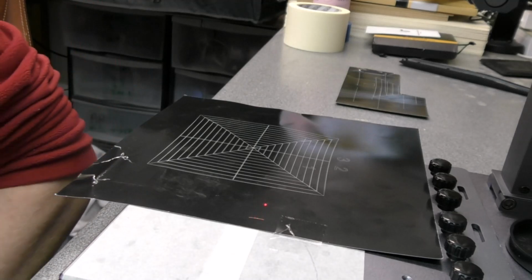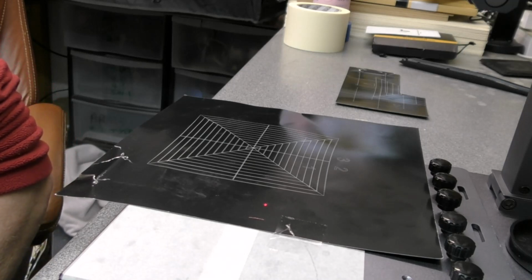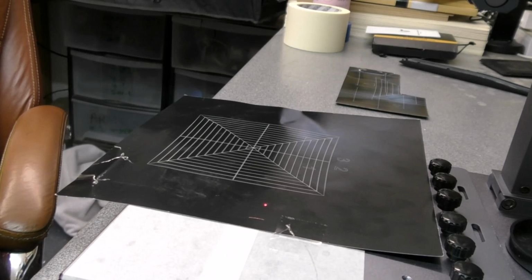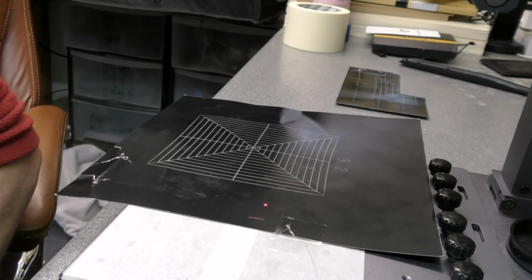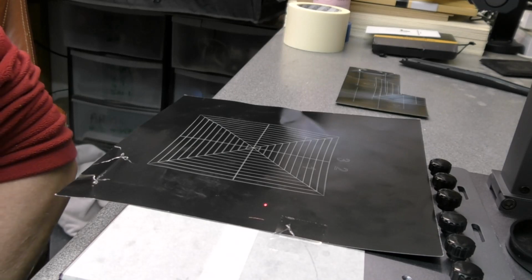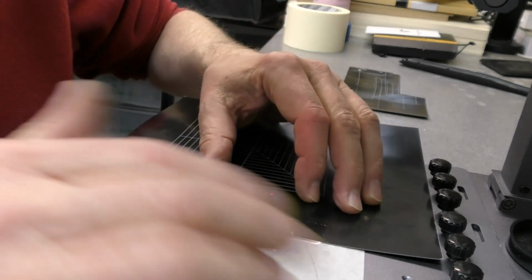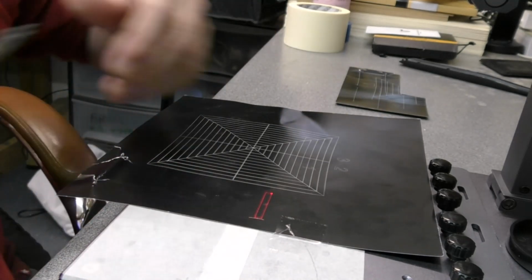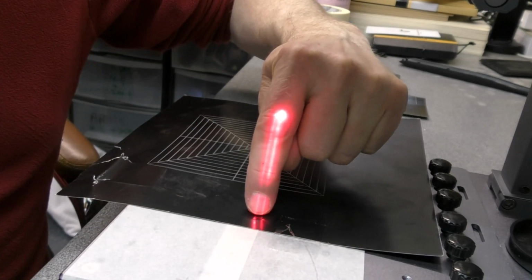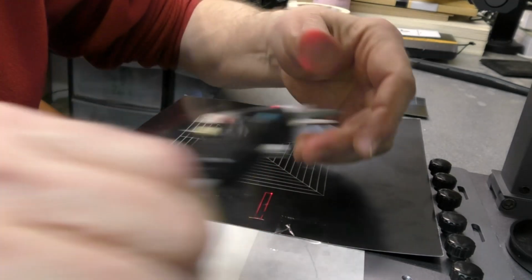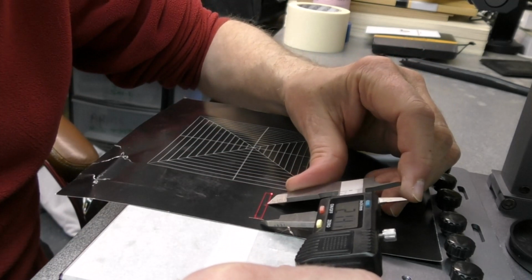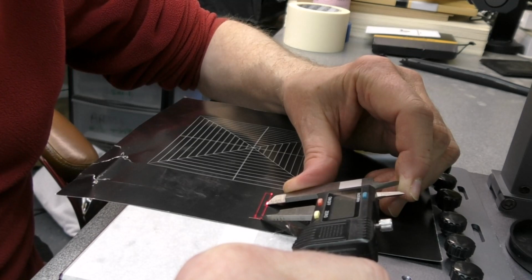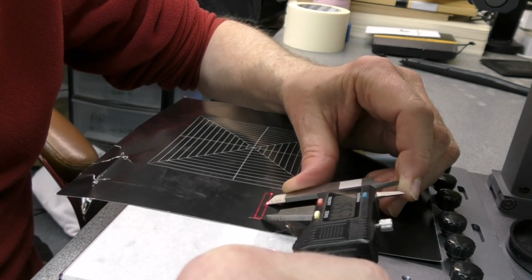So I'm going to go F3, red. We're going to change the offset back to 0.0700 and hit OK. Now we're going to do the red F1 again. Now this time, I really hope you can see this on the camera. This time the end of the box has been moved substantially back to where it was. So if we try and line this up now, we should be getting exactly 15 mil.